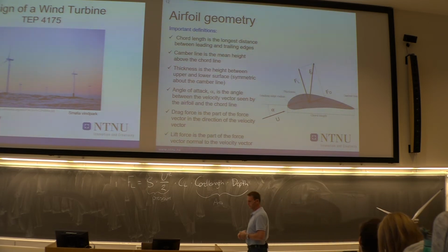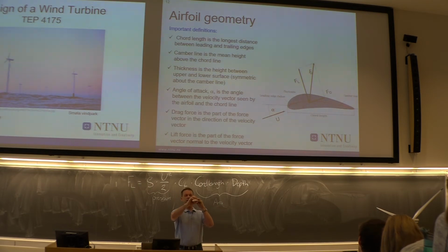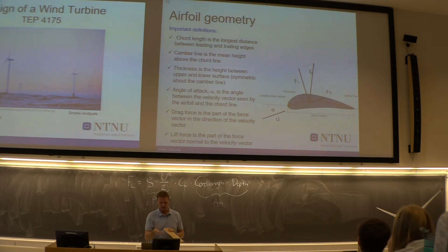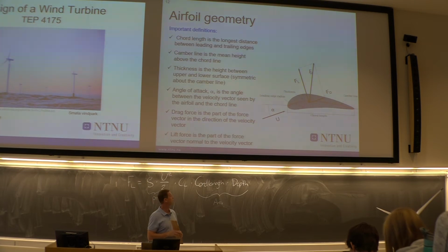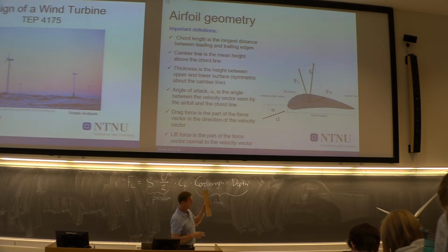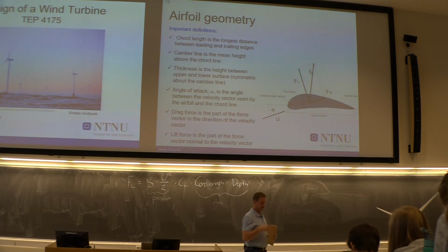The thickness of the blade is simply defined as the height between the upper and lower part. The angle of attack I have talked about. The drag force and lift force is something we need to define. And again, note that the lift force is always normal to the wind velocity.